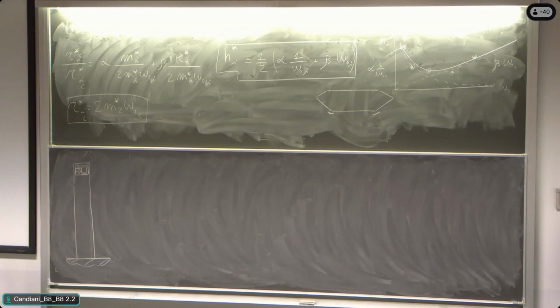Very interesting. All right, but I would like someone to tell me, what happens when I'm positioning a mass like that on top, tuned more or less at the same frequency of the mode 1 that I want to protect? From the analytical behavior of our studies, what happens? It happens that the mode 1 we are speaking about is disappearing. It's no more there. It's disappearing because it is here.